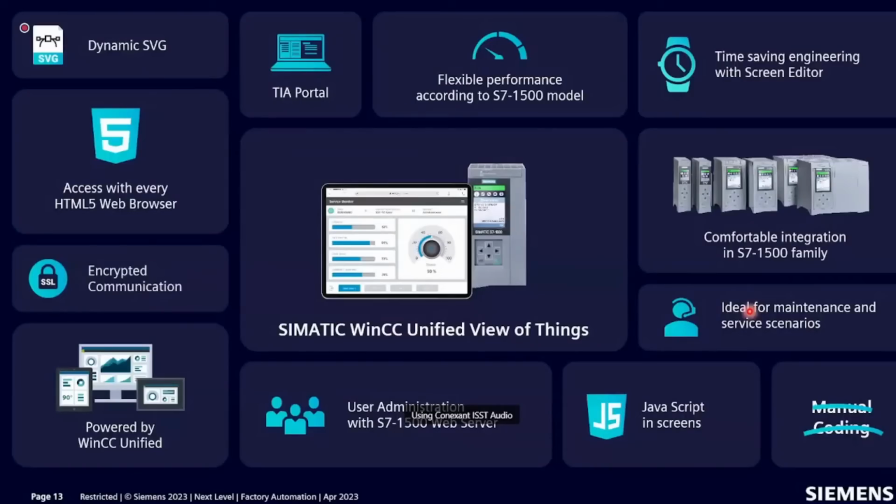So in VOT, we can use the same TIA Portal unified platform to develop the web page like HMI. Whatever objects are shown on the HMI screen, for example, all these gauges, widgets, trend and all, can be linked with the PLC web page in the engineering, and then deployed on the controller, for example, 1500 PLC. And then just by opening the web page of PLC, you can see a similar interface like HMI. So there is no difference.